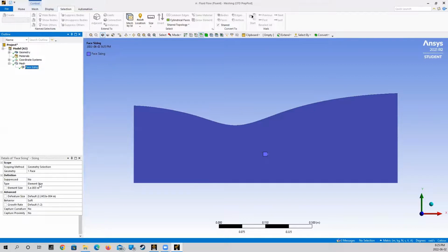It sort of just depends on how the elements stack on one another in our geometry. So by making the elements bigger, maybe they incorporate an area that would lead to a higher skewness if it was smaller, or maybe making the element smaller will fill up areas better. It can go either way.